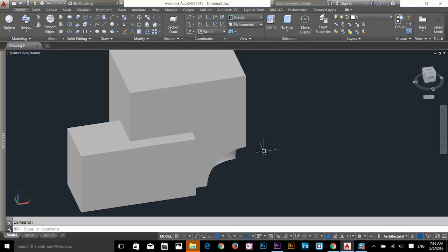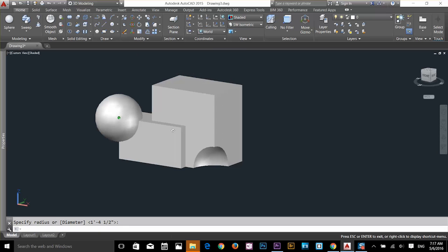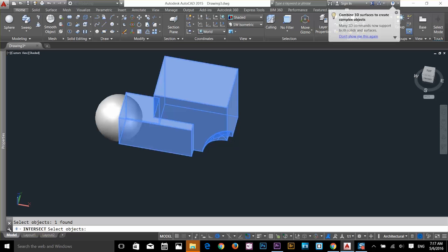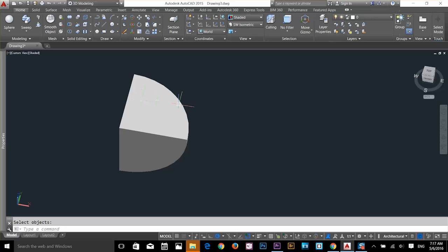This Boolean operation is very useful when you're gonna cut your window edges and door edges in your architectural modeling. So make sure that you get familiar with it. So now let's have a look at the intersection. Alright, so let's make another object here. I'm gonna make a sphere, and I wanna select my intersection command. I'm gonna select both objects at the same time, press spacebar, and now the object left was the one which was covering both objects.